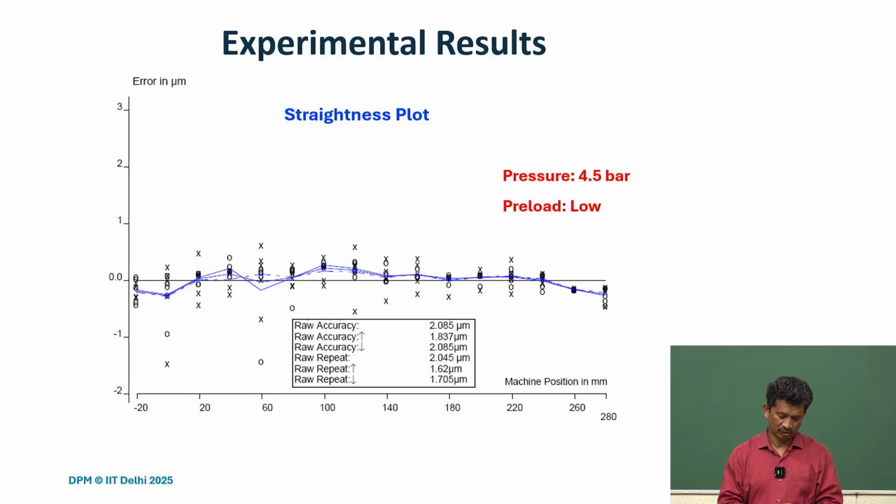Also, although the porous air bearing manufacturers claim that it's immune to pneumatic hammer, in reality, in practice, when you start building the system, you encounter the pneumatic hammer even in those cases. So yes, you always have to take those words from the manufacturer or the catalog with a pinch of salt, and you know the problems only when you start building things using those modules.